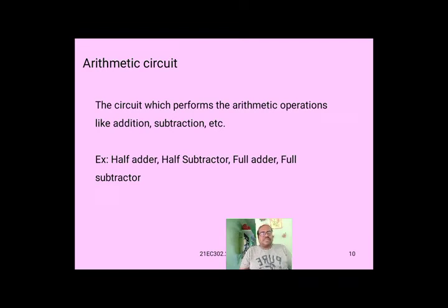Combinational logic circuit deals with the techniques of combining the basic gates that are intended to perform a desired function. Examples of such combinational logic circuits are adders, subtractors, multiplexers, demultiplexers, decoders, encoders, dividers, display drivers, keyboard encoders. Logic circuits without feedback from output to the input, constructed from a functionally complete gate set, are said to be combinational.